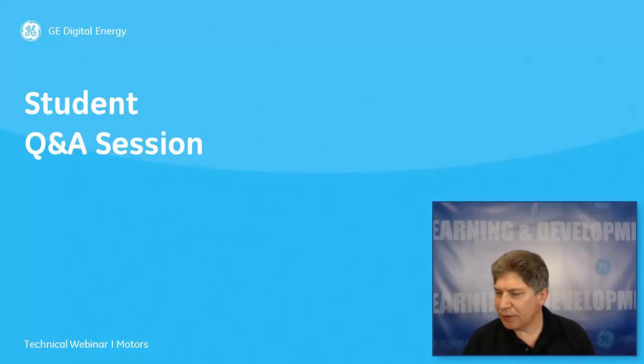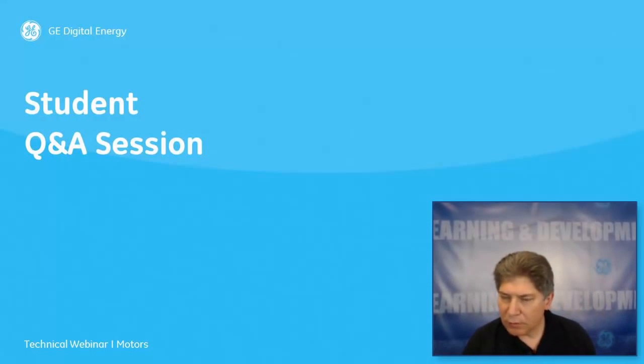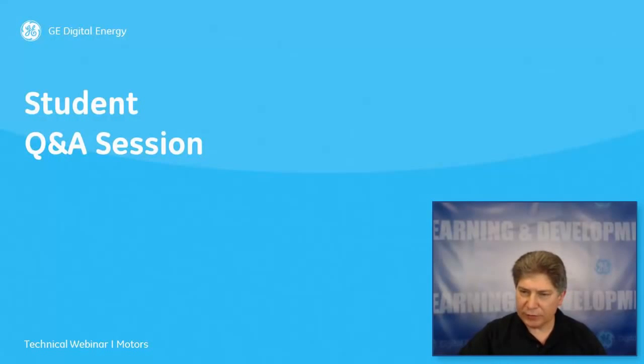Any other questions? George, this is Pat Kerrigan. Can you hear me? Yes, I can. I just want to comment on the last two questions. That twice the need is based on all the calculations you've done being based on AC symmetrical waves, and any kind of fault is likely to have a DC offset, maybe a full DC offset, and that saturates the CT in a different manner. Correct. So empirically, people use that two-factor because of DC saturation. It isn't quite accurate, but it's good for calculation, so that's why people do it.